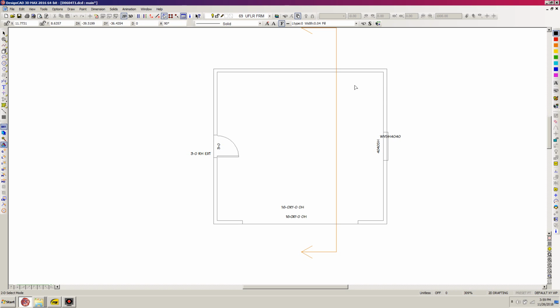We're also going to be using 1¼ inch BCI rim joist. I'm going to pull out a color that I'm happy with, and I think we'll use the blue for the rim joist. Let me click on that, so it changes it over here. I'm going to hit V for vector and H for orthogonal mode, and right-click at this corner and click on all 4 corners.